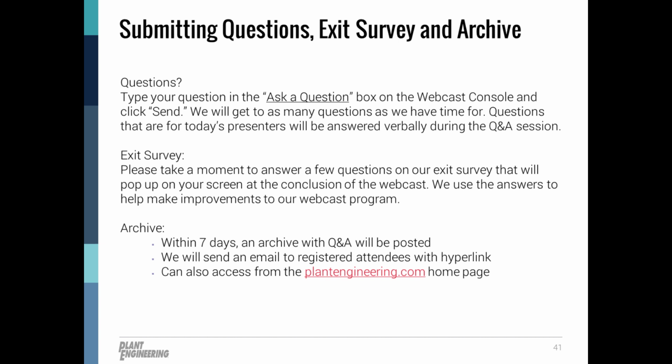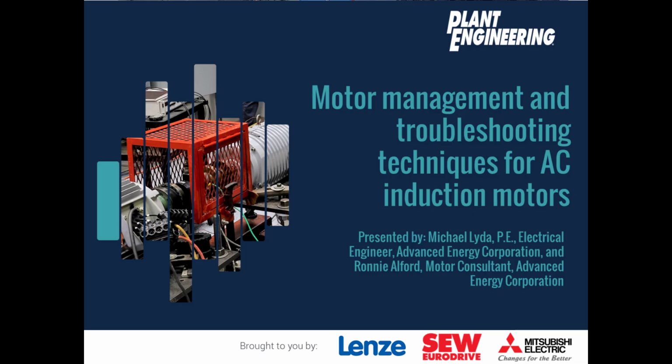There was another question in the Q&A about what to check voltage imbalance with. A simple multimeter is good if you have access to the motor terminals and do it safely. If you have some higher tech equipment, that's also good, but with a simple multimeter, you can check the three phases or each phase to ground, and you'll be able to tell right away if the numbers are the same or if they're quite a bit different.